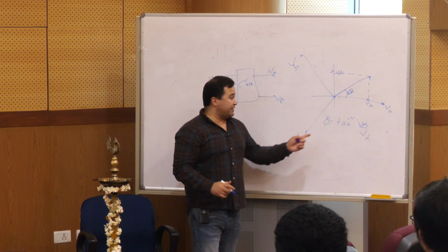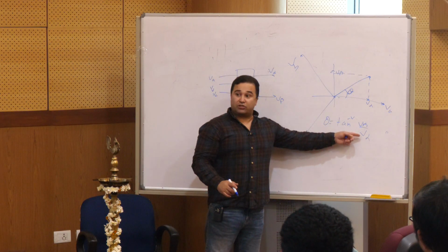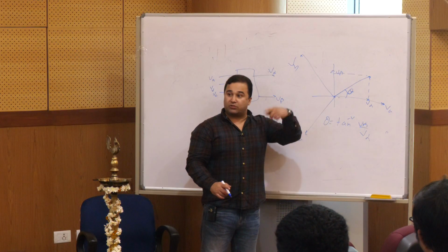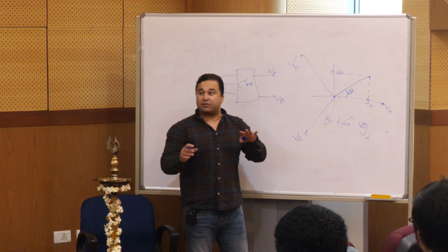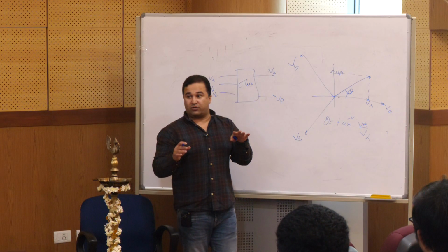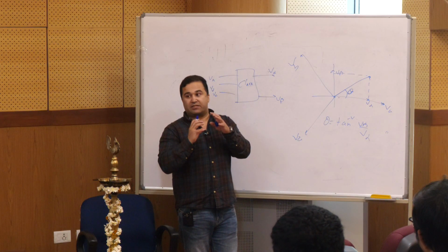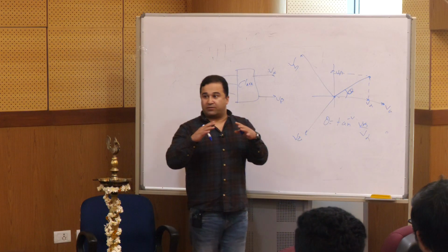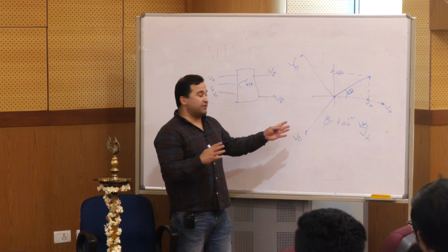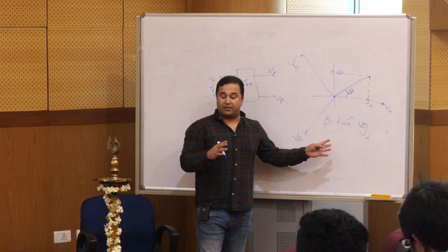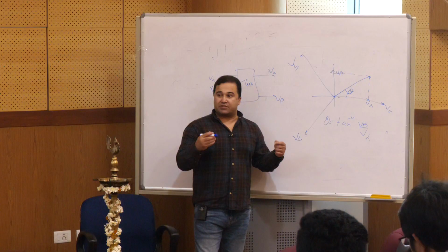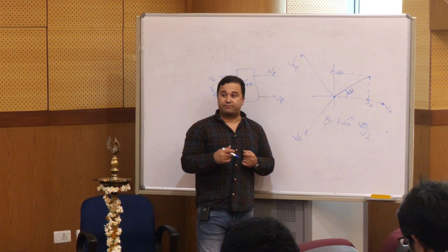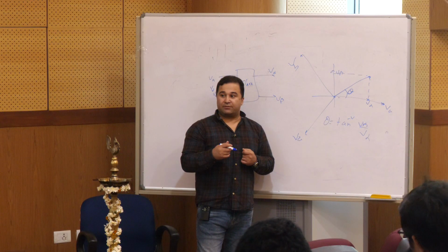Okay, so anything changing, the value of alpha beta changing, the theta changing, and the controller will be subjected to this change. So this makes a problem, and for this reason, the interface converter also gets some turbulence. Okay, so this is why the weakness of the PLL is that any disturbance happening, it gets into a problem situation. You got it?